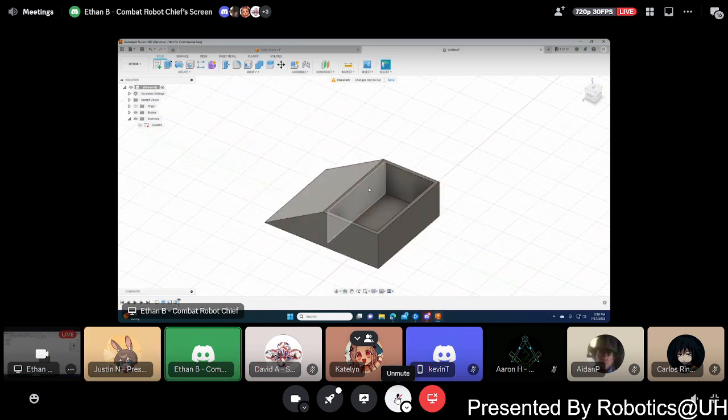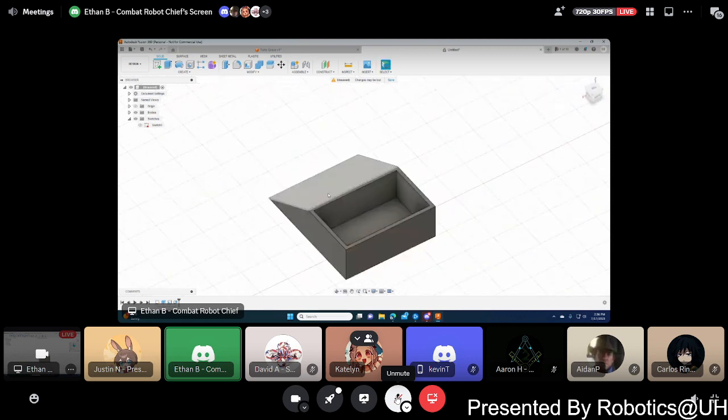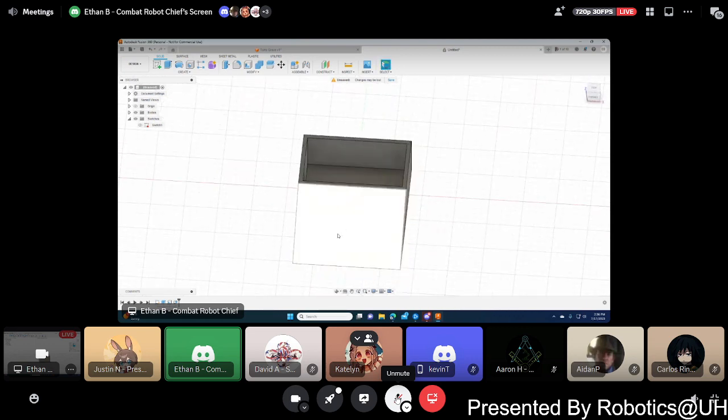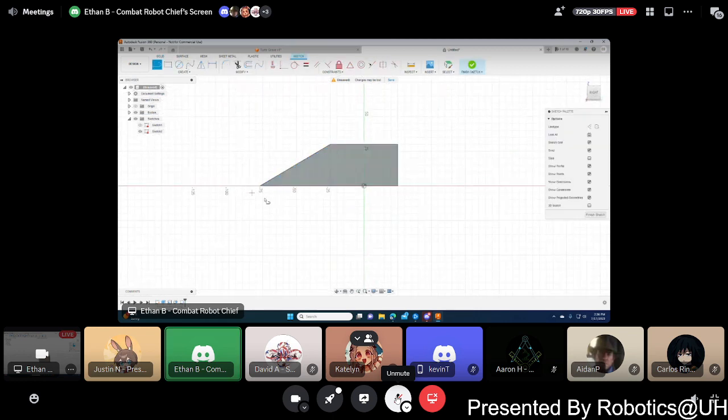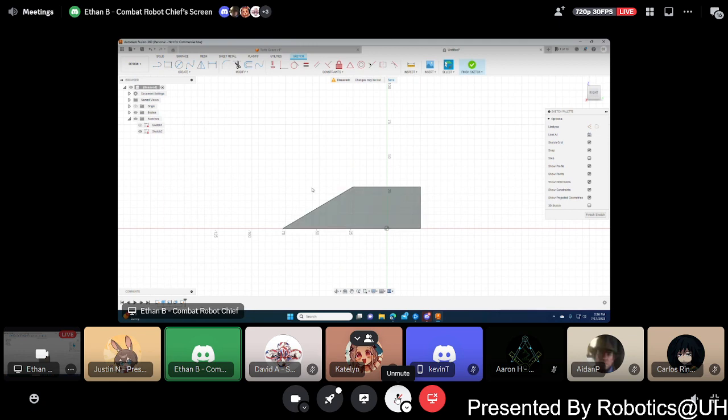So you could do that if you just want a solid box where you can do an extrude and cut a shape out of this. Let's see, I could do that right now. I'm going to create a sketch. Doesn't matter which one because I'm just gonna press escape and change it. What I like to do sometimes for making an arc is go into arc, then a 3-point arc.